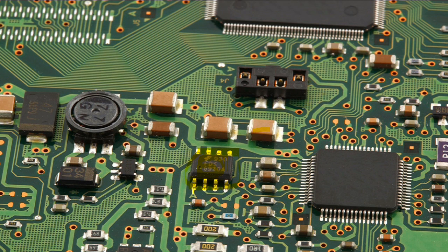So always pin number 1, pin number 2, pin number 3 are the source. These 3 pins are connected together, okay? The fourth pin of the MOSFET with 8 terminals is for the gate, and the other 4 pins or terminals are drain.